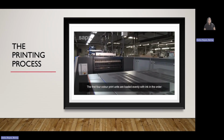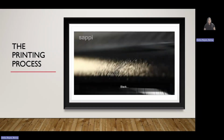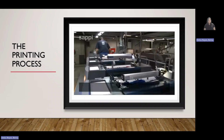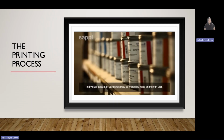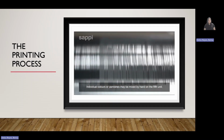The first 4 colour print units are loaded evenly with ink in the order black, cyan, magenta, and yellow. Individual colours or varnishes may be mixed by hand on the 5th unit.